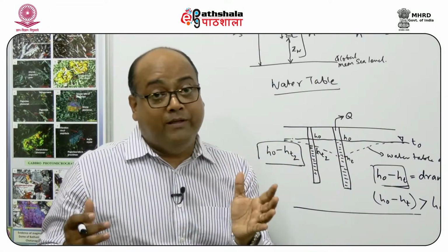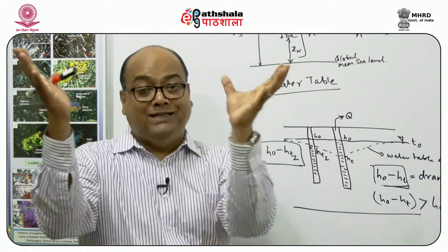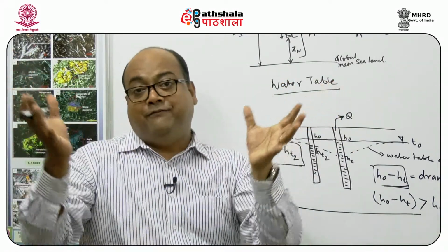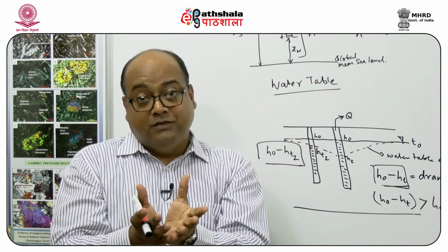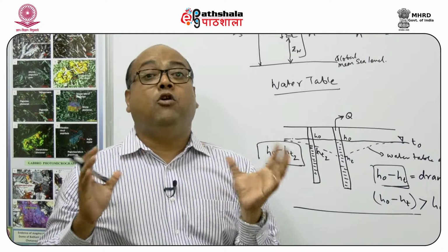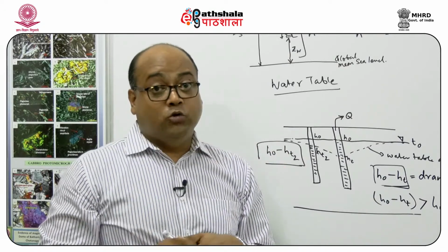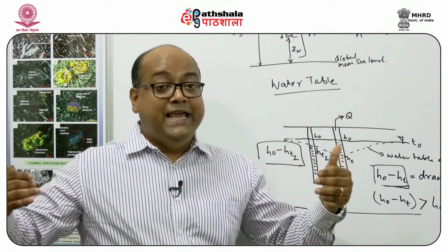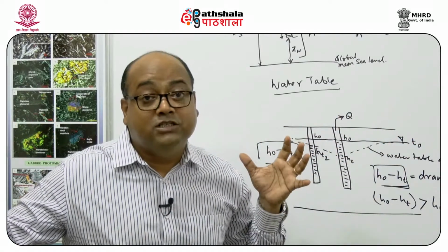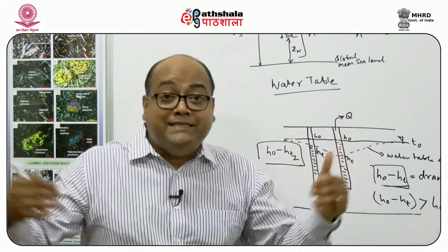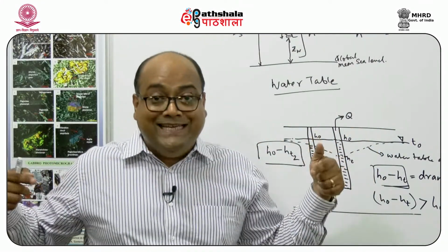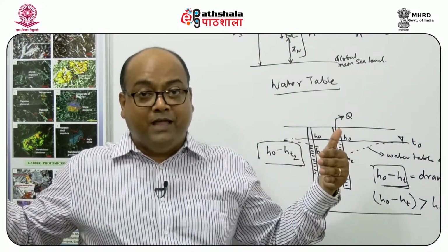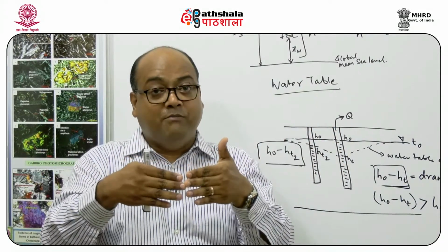So what we form here is sort of a cone. If you think of a funnel, it's like a funnel which is all depressing towards a common center. That's what we call a cone of depression. The movement of water, if we talk about a three-dimensional space, is moving like the spokes of a cycle wheel. The flow is merging from the outside towards a common center.